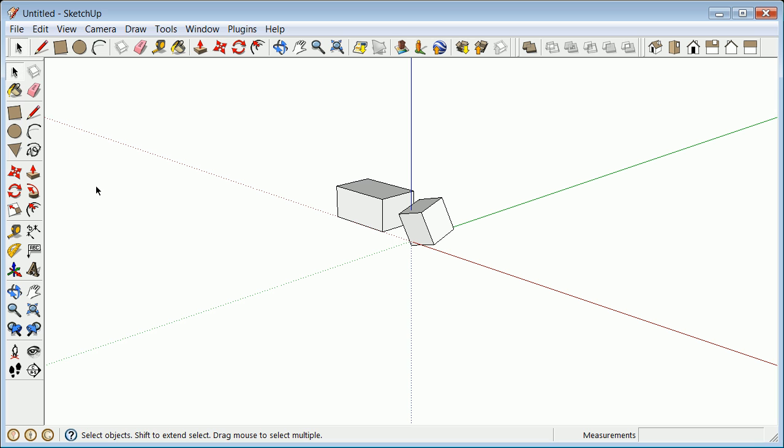The next thing that's key, so we've learned the shift key for holding a plane, the control key, or I believe it's the Alt or the Apple key on an Apple, is how we make copies. You do not want to necessarily, very often you don't want to be moving things. You're better off, if they're together, copying and then deleting. You'll see that later when we get into basic geometry work.